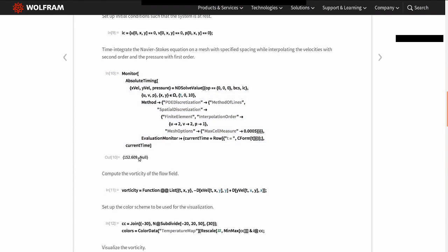So that's useful. Sometimes nonlinear time-dependent problems can take a long time to run, and you'd like to know whether the solver is still making progress, or whether it's somewhere in a bad zone where it's just hanging around and not really doing anything anymore. So that's a way to monitor something like that.